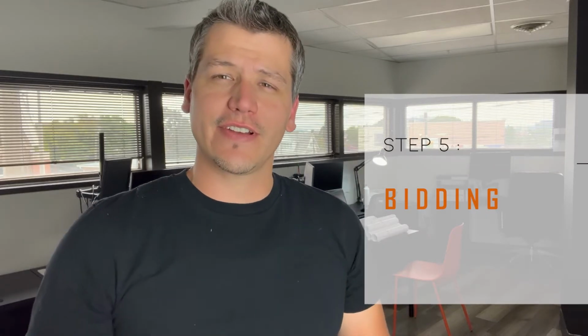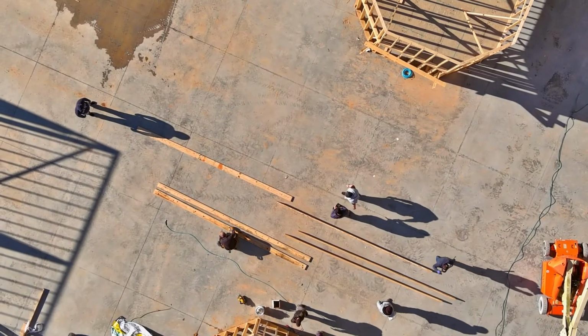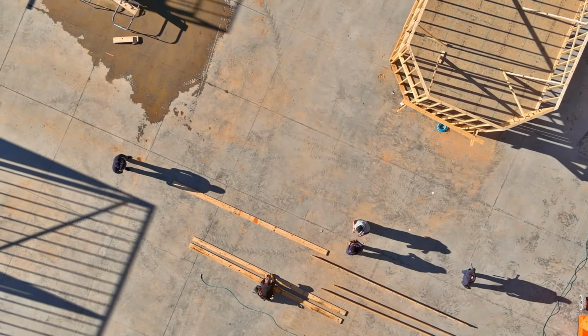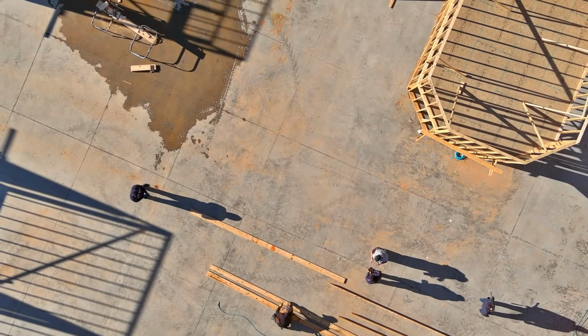The 5th stage in design is the smallest stage in design, and it is bidding. Bidding for a designer is mainly about coordinating and making sure that all the people affiliated with a bid are doing apples to apples bids. The last thing that we want to do in a bid is have one contractor bidding something different than another. A lot of times in the bidding process, we'll have submittals or value engineering, where a contractor will bring to the table a different product that they're used to seeing on their own job sites and issue it to the architect to see if it's an acceptable product for the design at hand. This substitution then needs to be communicated to all the other bidders to make sure that we're still getting that